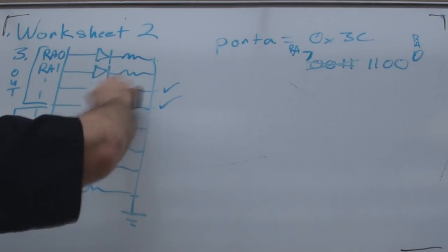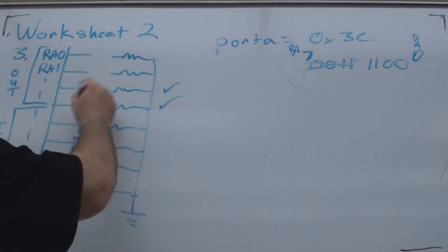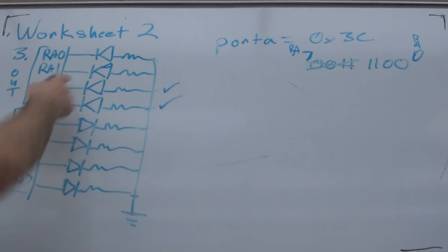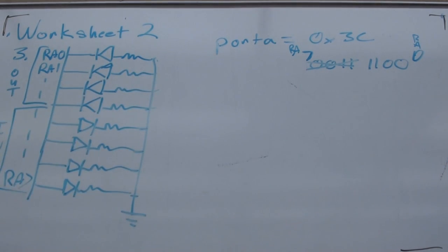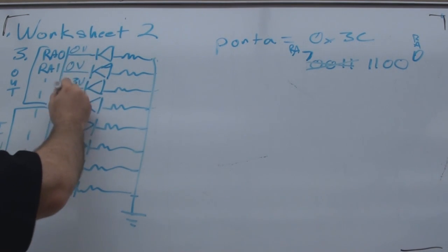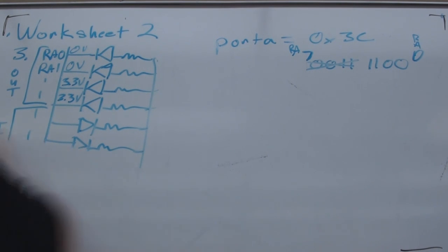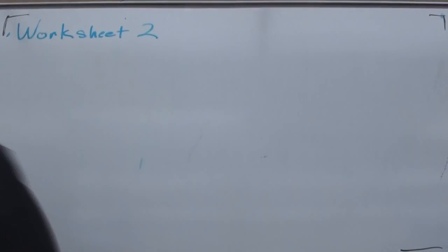That's just evil. So Michael's suggestion was, what if the LEDs were hooked up the other way? Now they're reverse biased. If you have a 1 here, so you've got 3.3 volts, because it's reverse biased, there would be no current flow, so no LEDs would come on, even if you energize the ports. And here you have 0 volts on either side, so there'd be no current flow. So these would be 0 volts, and these would be 3.3 volts, and no lights would come on in that situation.